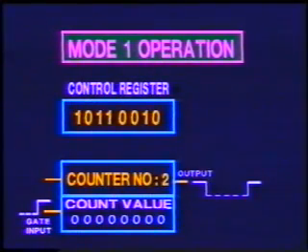The counter can be used as a triggered mono shot of desired width. The mono shot is re-triggerable. That is, a trigger at the gate starts the counting process. Before termination of the count, if another trigger appears at the gate, the counting starts again. Change in count value is allowed when the count is in progress. However, the change becomes effective only after the next trigger.